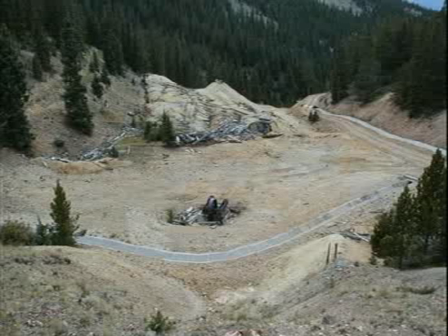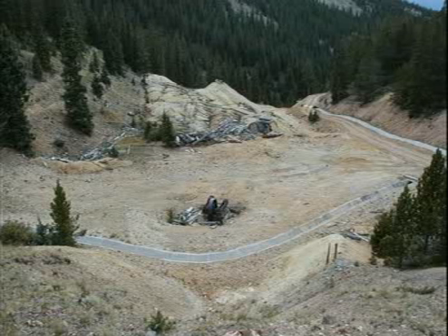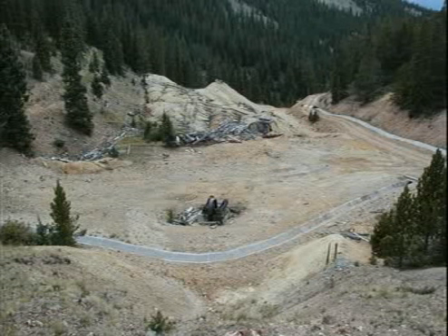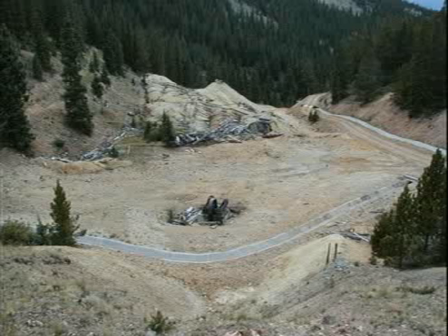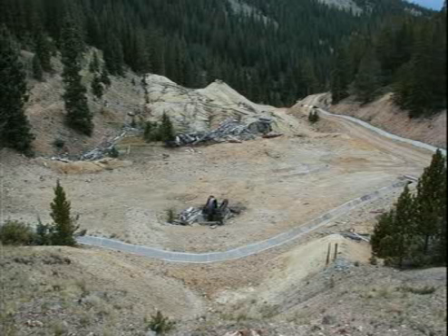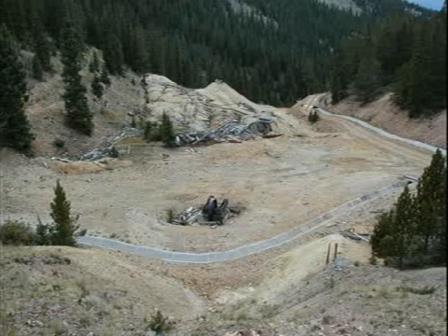There's a slide here that shows an example of an upland diversion ditch. This particular ditch is a concrete lined ditch, fairly simple construction. The ditch is that white line on the bottom of the diagram, and also on the right hand side of the diagram, and we're actually standing several tens of feet above a large waste rock dump, and the water is flowing from, say, my feet toward that ditch, and then it's supposed to flow across the waste rock. But the concrete lined ditch here will intercept that water and move it around the waste rock pile and keep a lot of the water out of the waste rock pile.